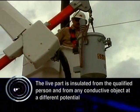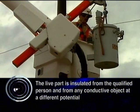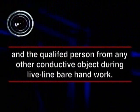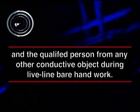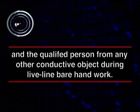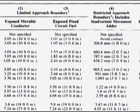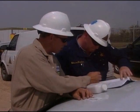The live part is insulated from the qualified person and from any conductive object at a different potential, and the qualified person from any other conductive object during live line bare hand work. Charts are available to determine the proper approach distances. Know how to read these charts and refer to them often.